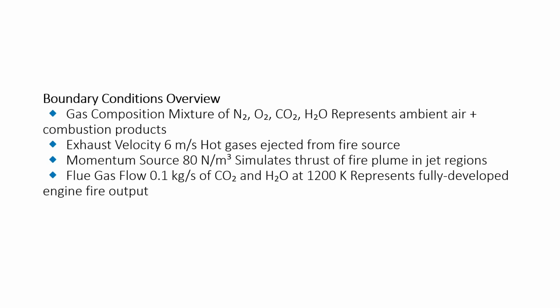Exhaust velocity: 6 meters per second. This is the velocity of the hot gases exiting from the fire source. It reflects the energy and pressure of the fire gases being expelled into the garage. Momentum source: 80 newtons per cubic meter. This represents the force per unit volume acting in the jet regions, simulating how the fire plume pushes and moves surrounding air due to combustion thrust.